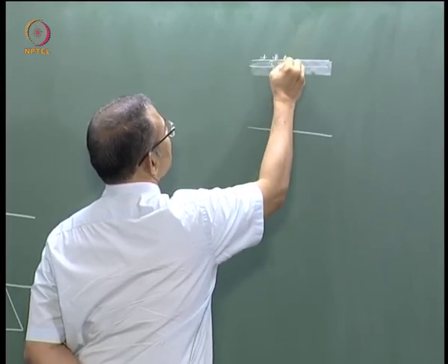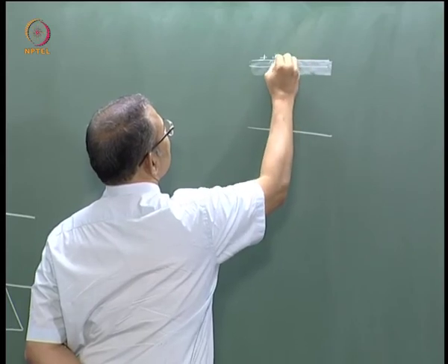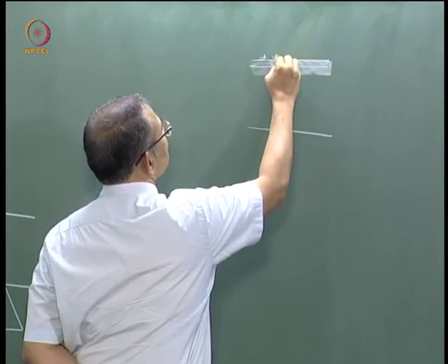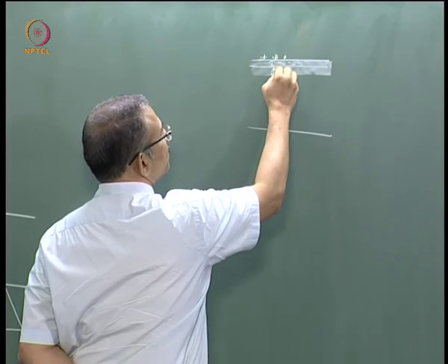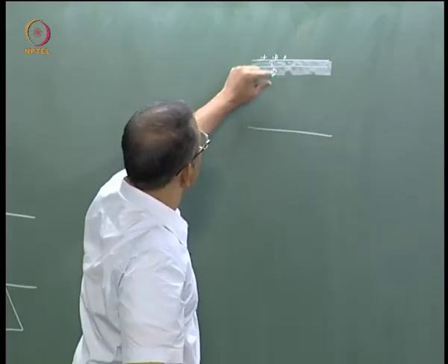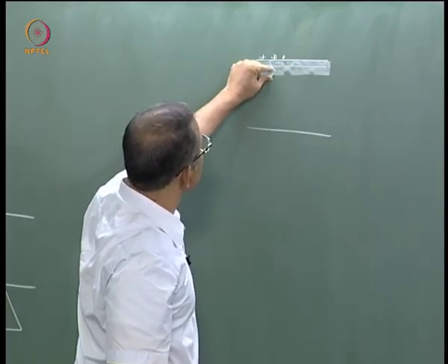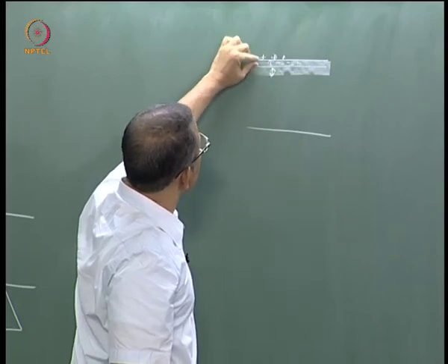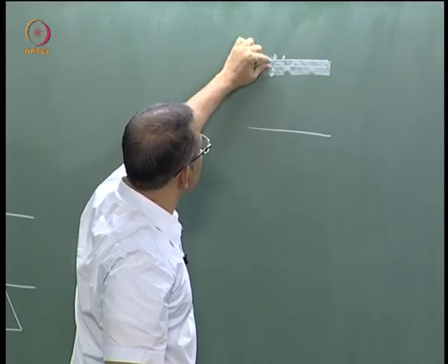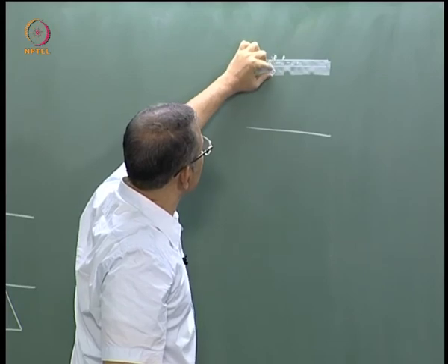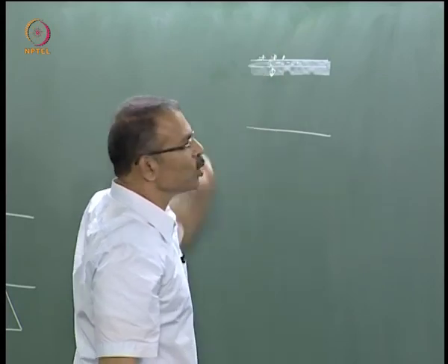Let us say if these are negatively charged electrons, then the field line from the positive charge would terminate here, it would not come to this point, right. That is why these mobile carriers are said to be screened by mobile carriers above, and therefore the effect of these charges on the mobile carriers is less. So this is the so called screening effect.